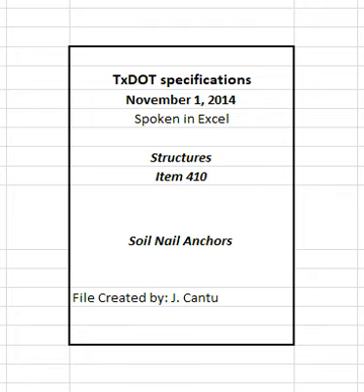4.3 Grouting. Place the soil nail anchor with centralizers that are spaced no more than 8 feet apart in the hole. Set the centralizers to position the soil nail reinforcing bar within 1 inch of the center of the hole. To grout, advance the grouting pipe to the bottom of the hole, and leave it there until the hole is filled with grout and enough unsegregated grout is expelled at the top of the hole. Withdraw the pipe slowly while grouting continues, filling the void left by the grout pipe.